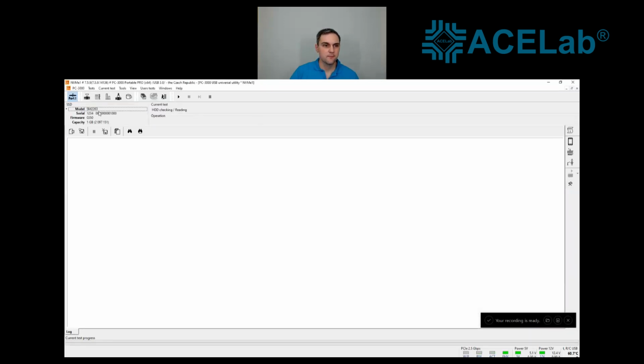And the same as for any other Silicon Motion 2263 drives, it goes into safe mode by default, because again the problem here is connected with the damaged firmware, damaged translator. So the drive stopped working correctly and shows us just a limited capacity and the controller passport ID, but not the SSD passport ID.